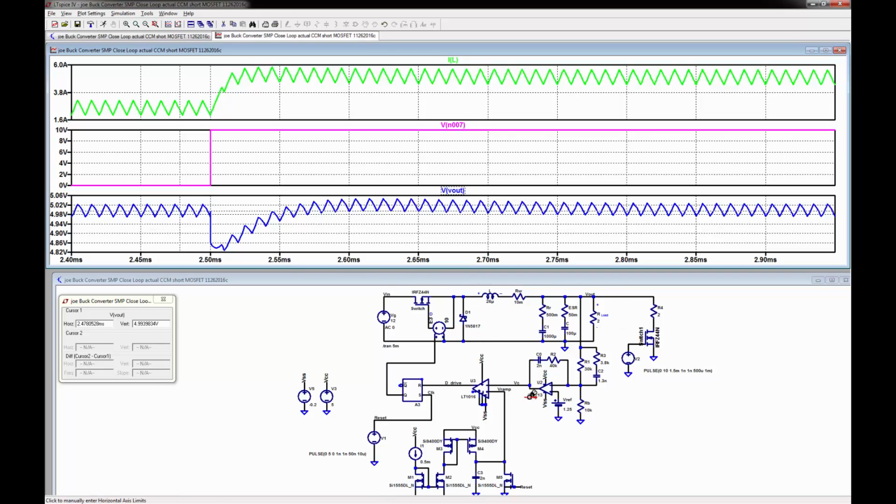And that you'll see, as we lectured, is the open loop output impedance divided by 1 plus T. And that varies, that will be our output impedance, and then you have to look at that times the 2.5 amps will give you a set voltage. We actually set this to 5 amps, that's why it was 5 volts at 5 amps, but then when you go to a different current, it scales down because of the drop across the internal output impedance divided by 1 plus T times the current. Okay, so this is pretty cool, so let's look at the other end to show you that it jumps up.